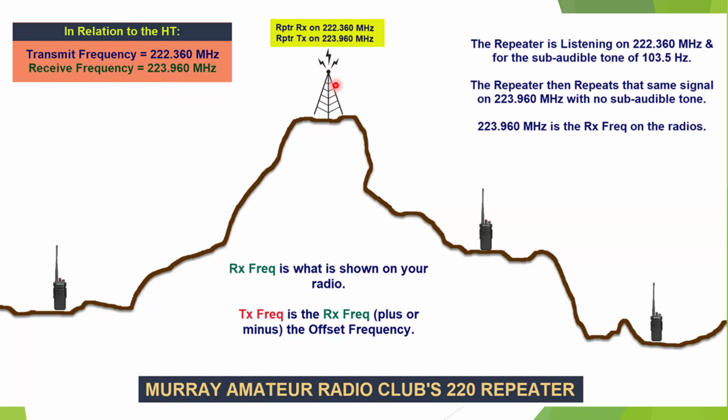On the repeater side, it's just the opposite. The repeater receive is 222.36, and the repeater transmit is 223.96. So when we look at our radio, we're looking at the frequency 223.96, right? That is the receive frequency. That is the frequency that the repeater is transmitting on.